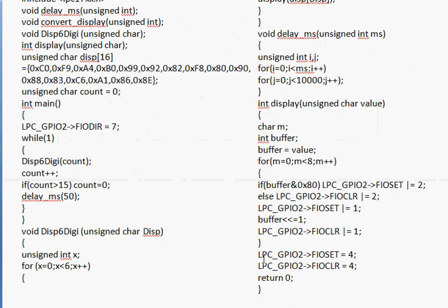What is used for the latch is the P22 pin. So for transferring the data onto the 7 segment module, first the P22 pin should be made high and then made low. A small amount of delay is fair enough. So this is for providing the latch. In this case, the 8 bits will be transferred onto the 7 segment module. So this is how the structure looks, and this is what happens when you provide this function.